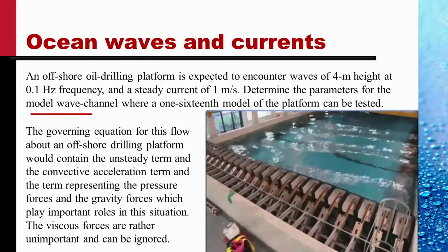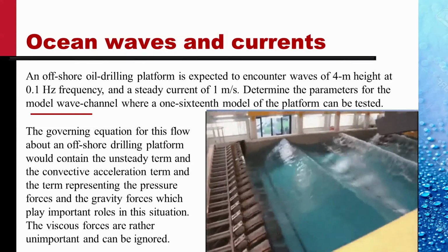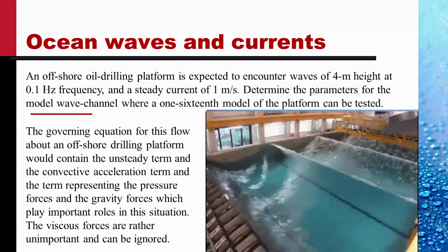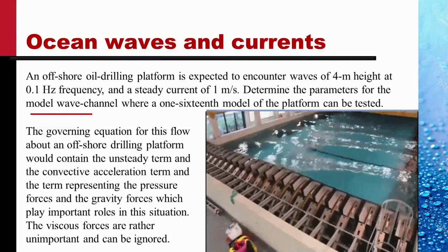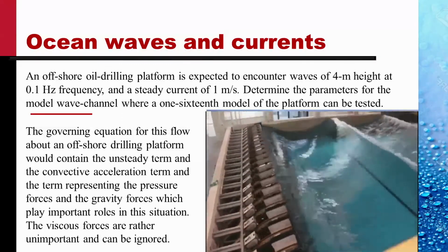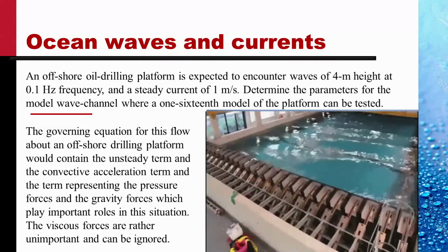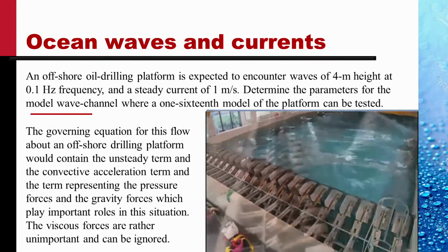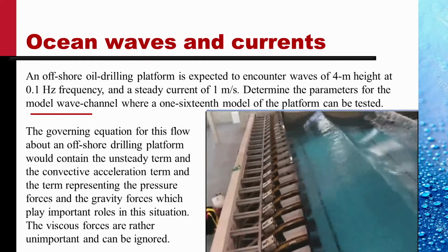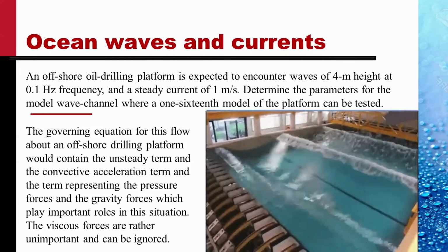The governing equation for this flow about an offshore drilling platform would contain the unsteady term and the convective acceleration term because of the steady current, and the term representing pressure forces and gravity forces which play important roles in this situation.